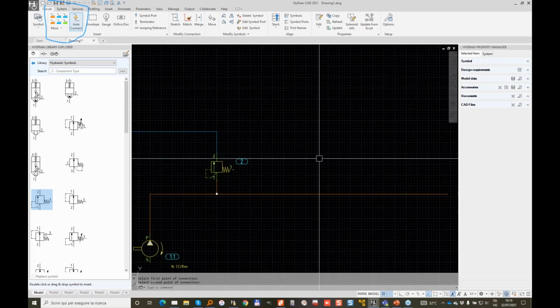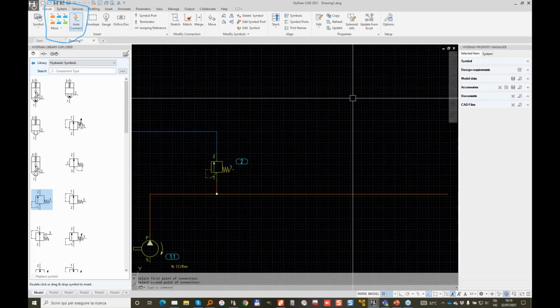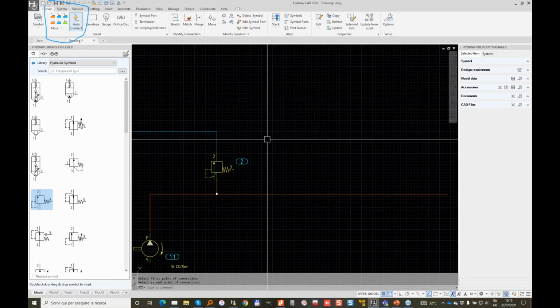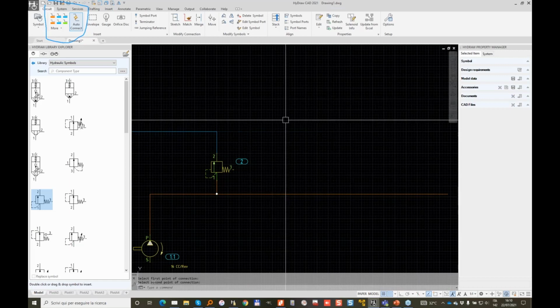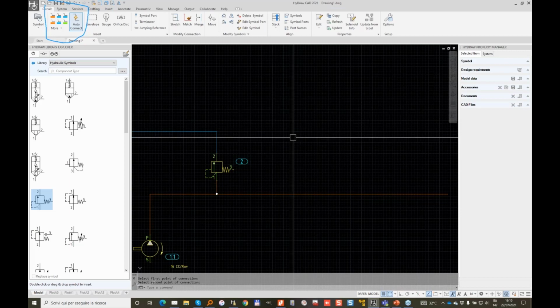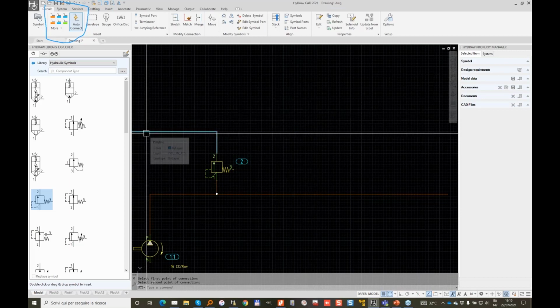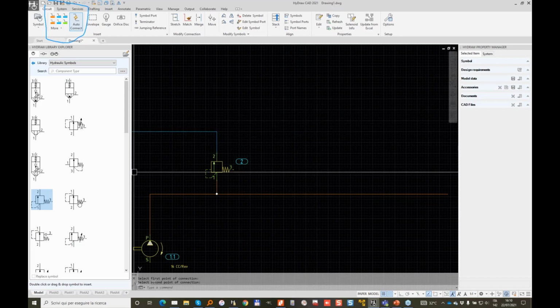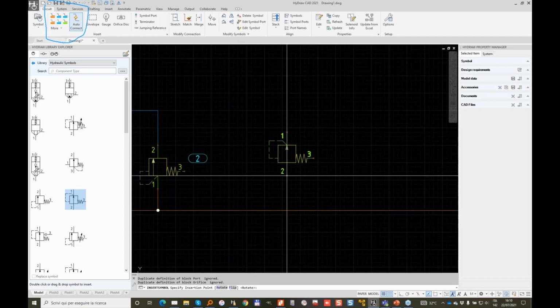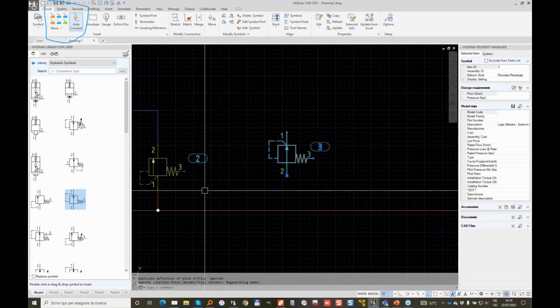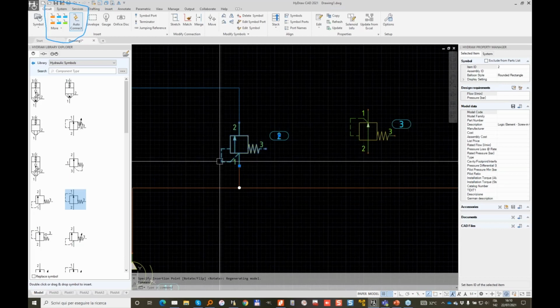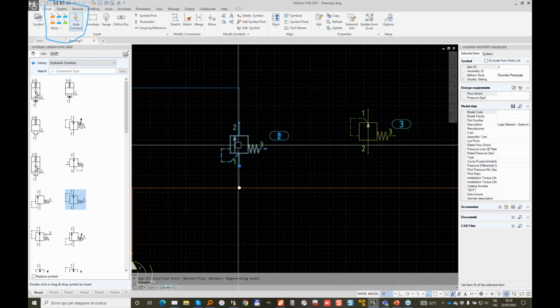So now I want to build something like a sectional valve. So this is common application in sectional valve, but I will build with the standard cartridge and surface mounted valves. So I need a normally open pressure compensator, this one. And well, let me first specify a component for this.